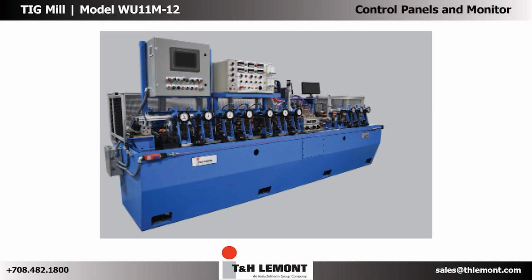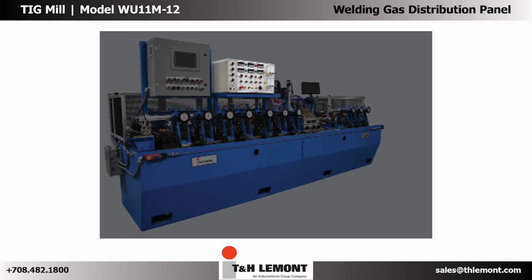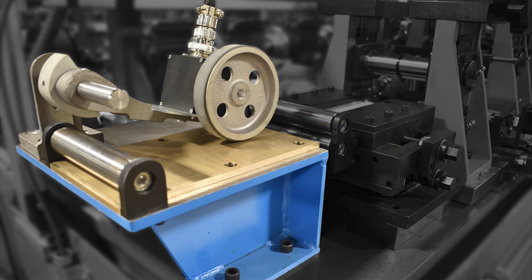This brings us to the mill. At first glance, the most noticeable things sit on top. First is the mill's control panel. Second is the gas distribution system for the welding unit. And last is the monitor for the welding camera. Moving in for a closer look, the first item is the encoder. The encoder's wheel rides on the strip surface to measure its length.